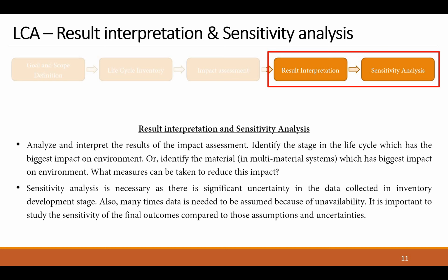Many times while performing the life cycle analysis, we have to make several assumptions about how our product is going to be used, or sometimes because of unavailability or proprietary reasons, we don't have any values of inputs or outputs. In that case, we have to assume those values. So we have to make sure how much impact or how much uncertainty those assumptions impart in our final results, in our overall impact score. Depending upon that, the interpretation of our results might vary significantly. So that's why sensitivity analysis is very important to perform.